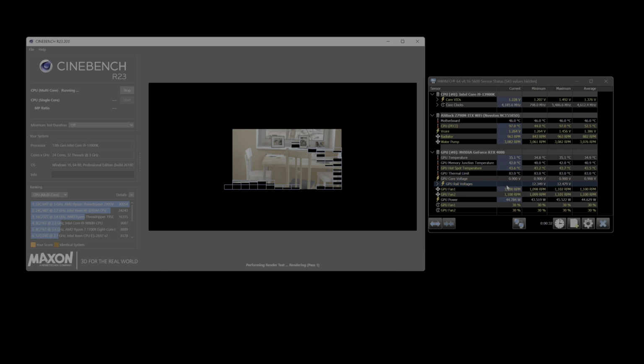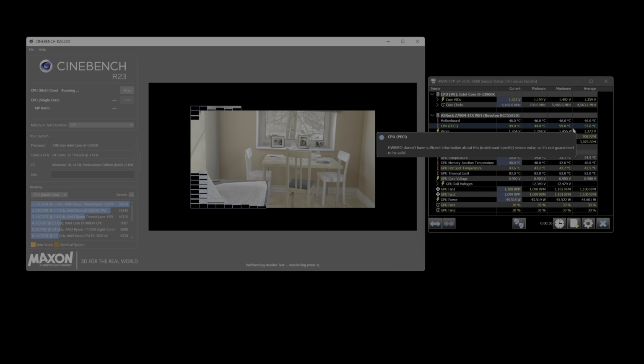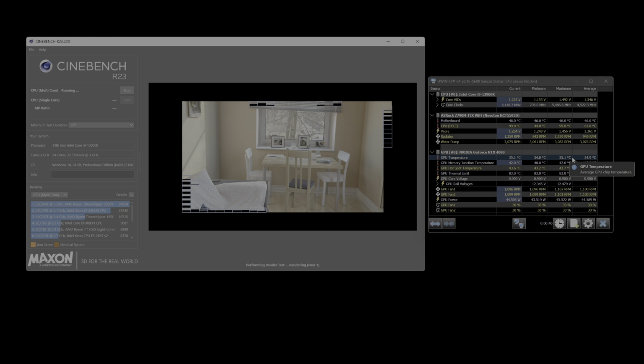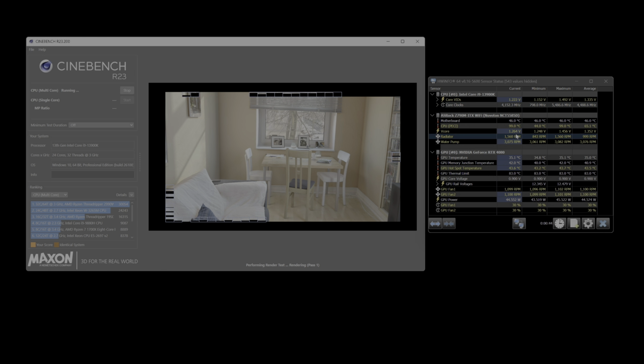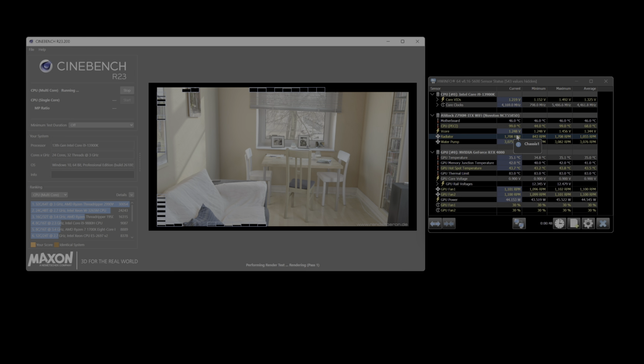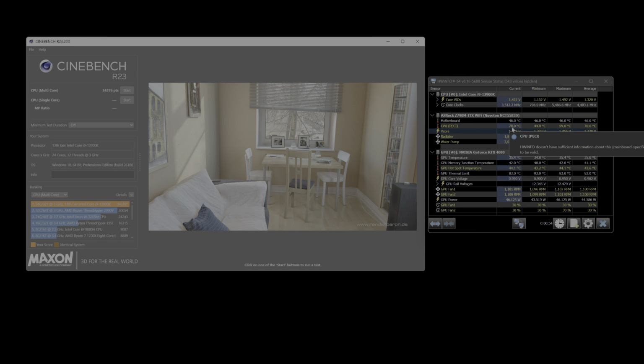And immediately what you're probably going to see is that my processor is running up to 100 degrees thermal. My voltage is 1.23, 1.26, so I'm a half a point or so, maybe, yeah, half a point off, which is pretty close setting overall. When you're running at a max setting here, these numbers should be very similar, and if the BIOS manufacturer has those numbers right in their default settings, then it should put you in that range.